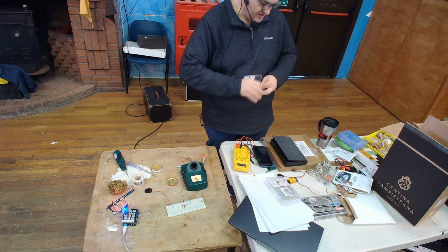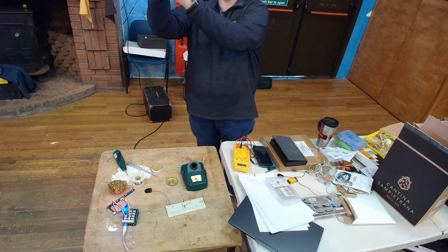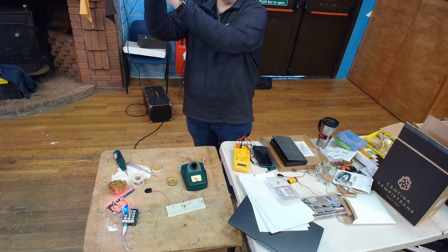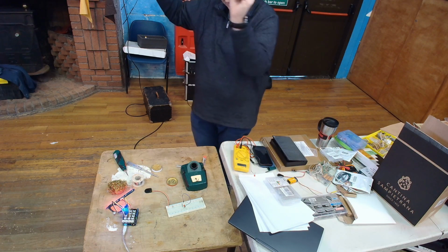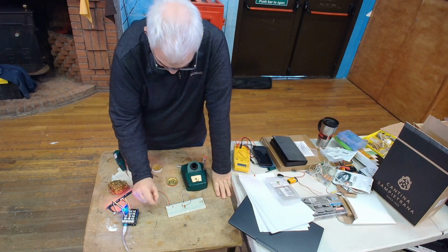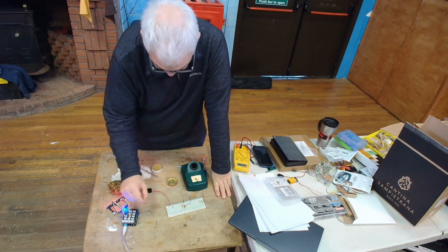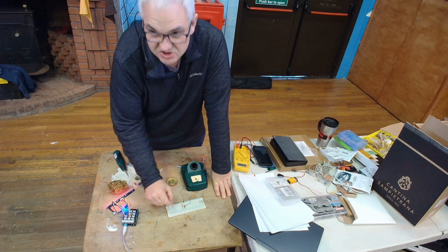So when you're in the burglar alarm at home, there's a magnet on the door that's close to the sensor and it keeps the switch closed, and then when you open the door, the magnet moves away and it opens and it's detecting that. So you can use exactly the same thing to bring this in. When the magnet's close, you've got a switch that works.